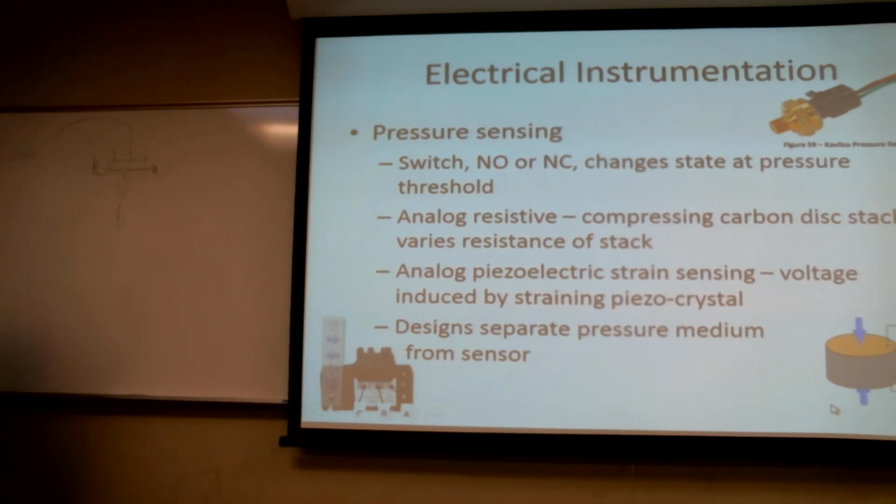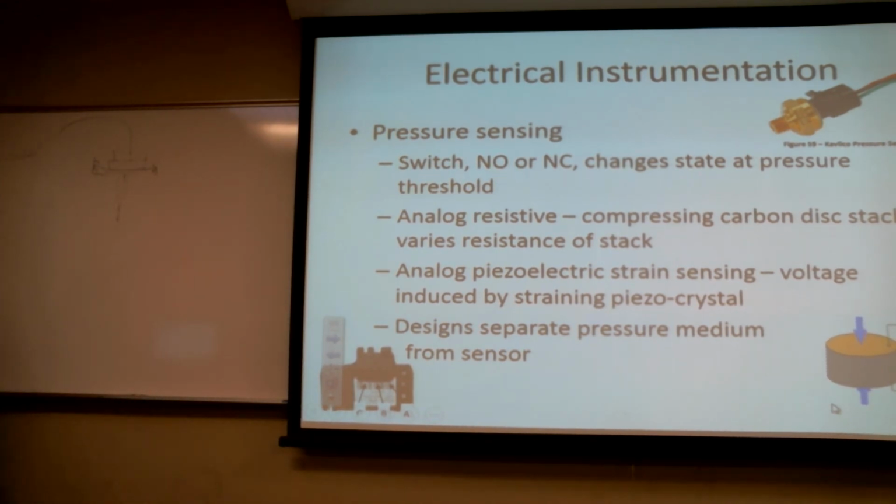A third one is what's called piezoelectric strain gauges. I'm not going to dive too deep into piezo crystals, but piezo crystals are voltage generators. And as you strain them from their natural relaxed crystal state, they start causing current being transmitted across one polarity to change direction, and on a different axis, you'll start measuring voltage. The more you strain it, the more voltage you sense.